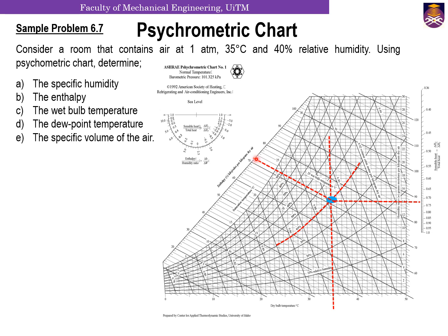that will be the enthalpy of that problem. Now to find wet bulb temperature, we need to draw a line parallel to the wet bulb lines here. So to do that, first we will find the dew point temperature again. To find the dew point temperature, all you need to do is you draw a straight line, horizontal line, until it intersects to the saturation temperature line here. So the line that cuts the scale here will give you the dew point temperature. All right, so you can find the dew point temperature based on that.